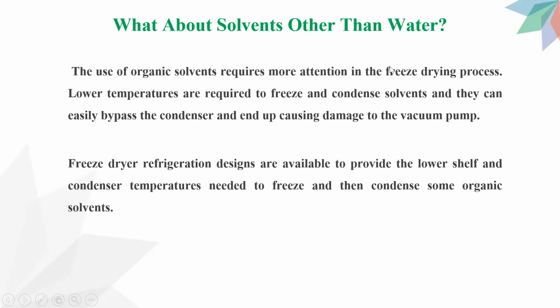What about solvents other than water? Most freeze dryers work with water, so what about the use of organic solvents? The use of organic solvents requires more attention in the freeze drying process because these organic solvents are characterized by a lower freezing point. Lower temperatures are required to freeze and condense solvents, and they can easily bypass the condenser and cause damage to the vacuum pump. Freeze-dry refrigeration designs are available to provide the lower shelf and condenser temperatures needed to freeze and then condense some organic solvents.